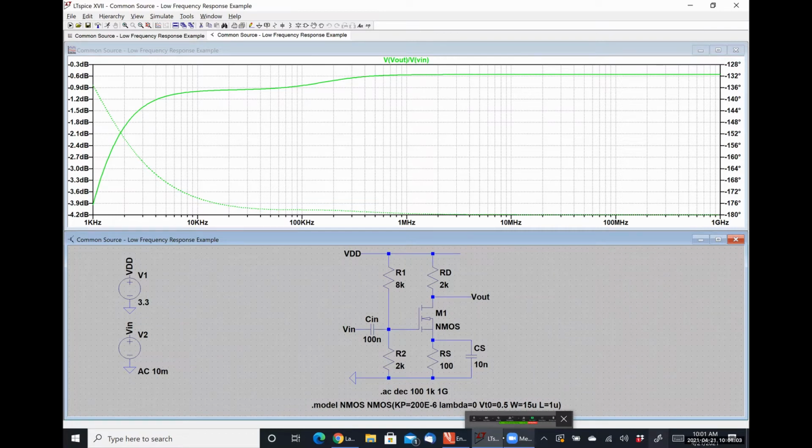We can loosely say that every location in our circuit that we have a capacitor should contribute a pole if and only if the locations of those poles are far away from each other. Meaning, if the capacitors don't interact with each other. We'll see when we look at the high frequency analysis where there is capacitor interaction because of a Miller capacitance between the gate and the drain, that we're still only going to look like we have two poles even though there's more than two capacitors. But anyway, I just used this where we had no R sig because it should be largely familiar to you guys since you did it as a project.